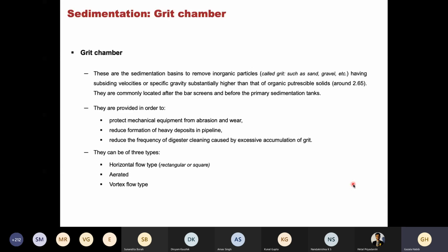Sludge digesters are generally used to thicken the sludge and dry it, and even to kill the bacteria and make the sludge free from bacteria, and also to make it thick enough so that it can be disposed of. It will not remain bulky and can be disposed of easily.